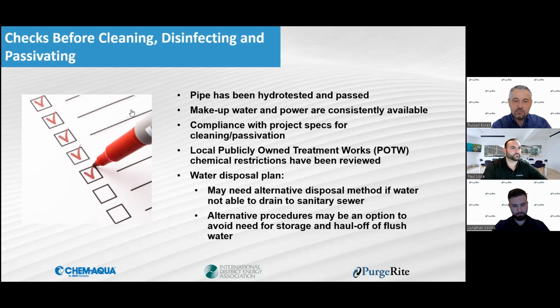The mechanical engineers design systems to operate. That's what they're paid to do, and that's what the design work revolves around. But the flip side of that is sometimes thought doesn't go into both the specifications and into the design of how we're going to clean this thing initially. Operational velocities and things like that are not necessarily the same as flushing velocities and what it takes to clean these systems.